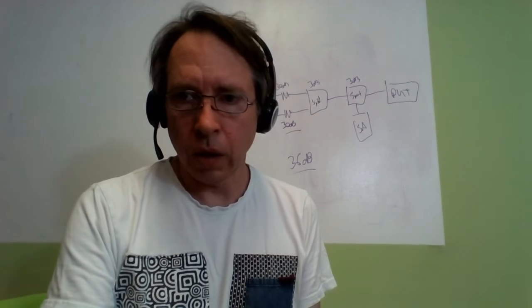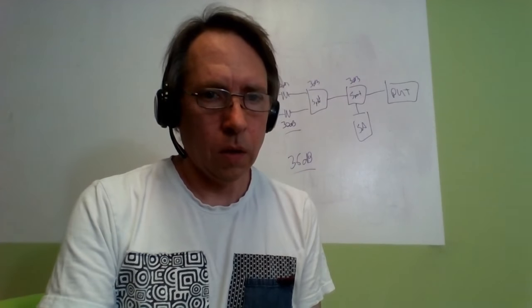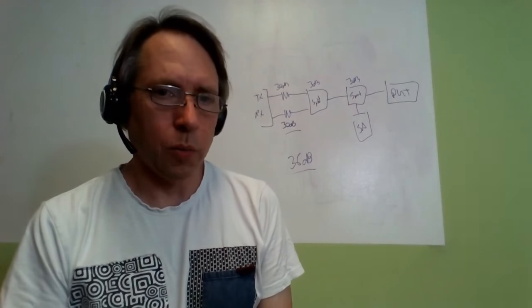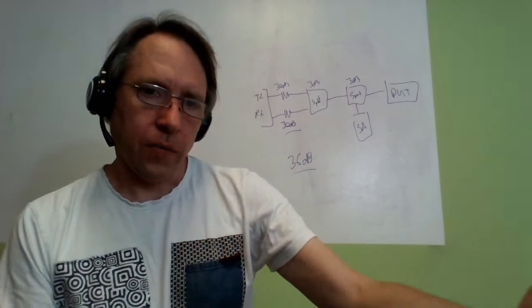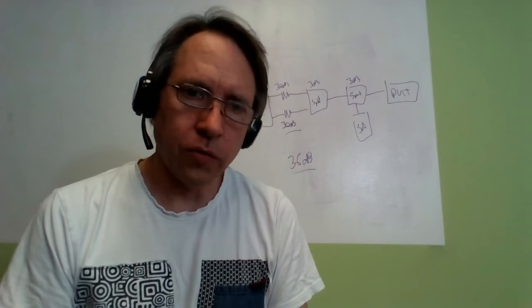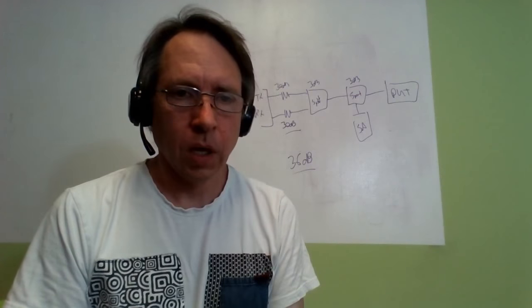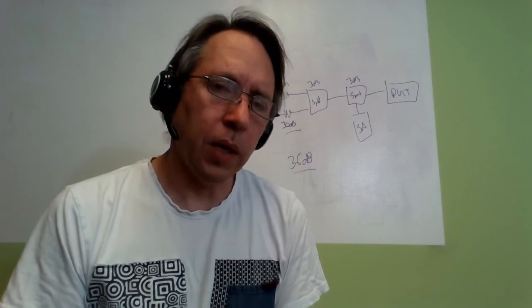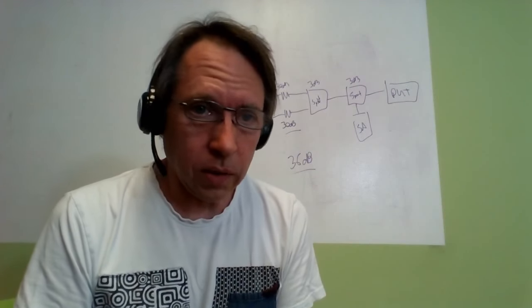Similarly, on the downlink, the device under test is reporting back that it sees the signal from the LabKit at negative 81 dBm. And by taking a reference measurement with a known good device, we know that this is normal.